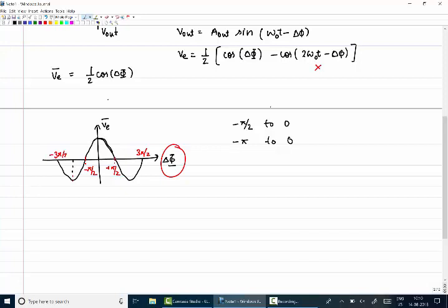Which is the largest range you think will ensure that you are always in the negative feedback? Minus pi to 0, this one, right? So I can say that if my phase error is within this range, minus pi to 0, then the PLL will always be in a negative feedback. The feedback will not change the sign, and it will always try to bring the output close to the input in the feedback loop.